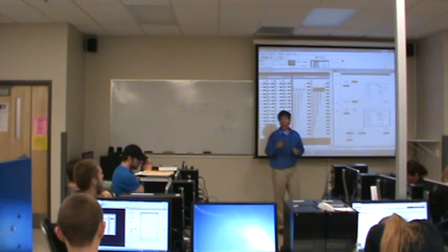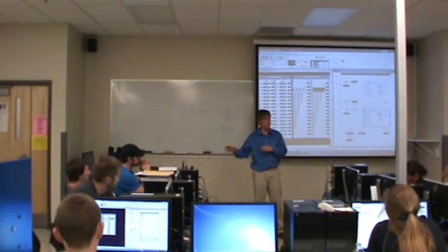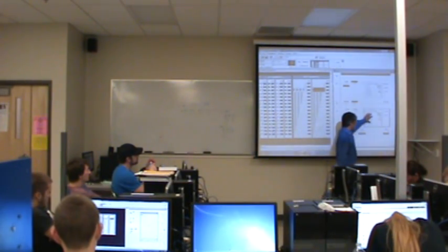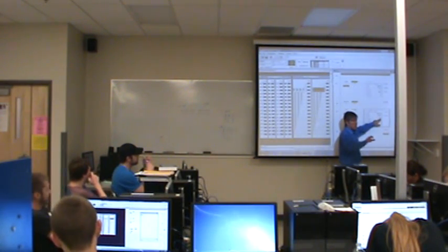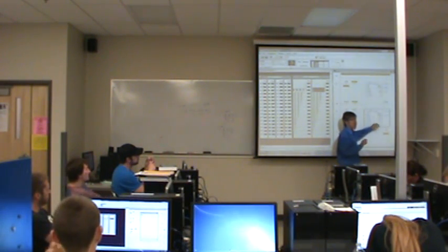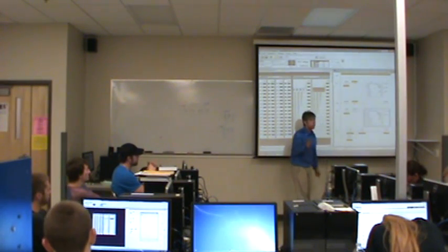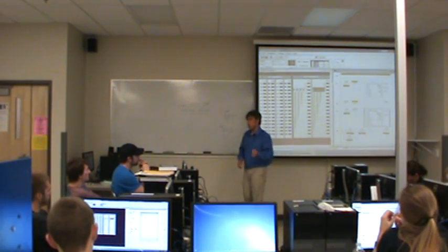Well, in the mask move, what I'm doing is I'm simply putting the data into memory, in the binary file. So I'm preventing the mask moves from affecting anything else in the binary file. This instruction grabs data from the binary file and puts it into the outputs. So this is masking and preventing me from writing anything into these outputs, which is a totally different place than the data in memory, which is in the binary file. Does that make any sense?